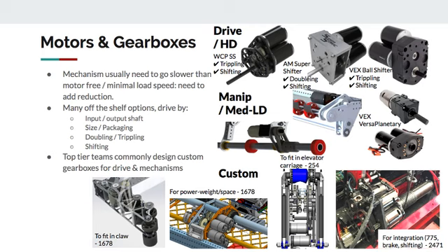Because there's been this whole thing between big heavy Sim motors and smaller 775-like motors, the gearboxes have also fallen into those two categories up to now. So at the drive side, we've been using these VEX ball shifters for a long time. They let you put things like 1, 2, 3 motors in. You can get shifting versions, you can get non-shifting versions.